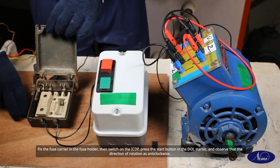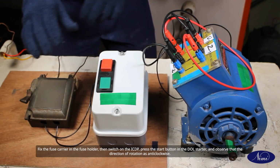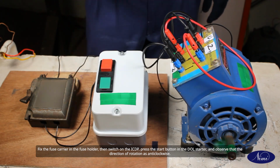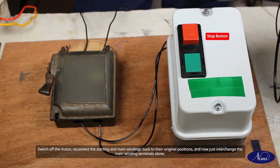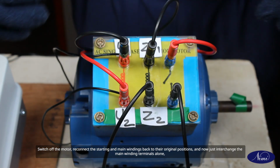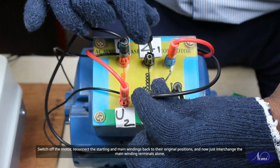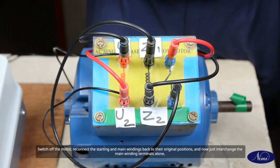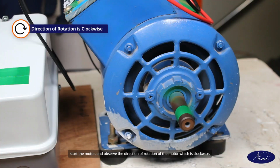Fix the fuse carrier in the fuse holder, then switch on the ICDP, press the start button in the DOL starter and observe the direction of rotation as anticlockwise. Switch off the motor, reconnect the starting and main windings back to their original positions, and now just interchange the main winding terminals alone. Start the motor and observe that the direction of rotation of the motor is clockwise.